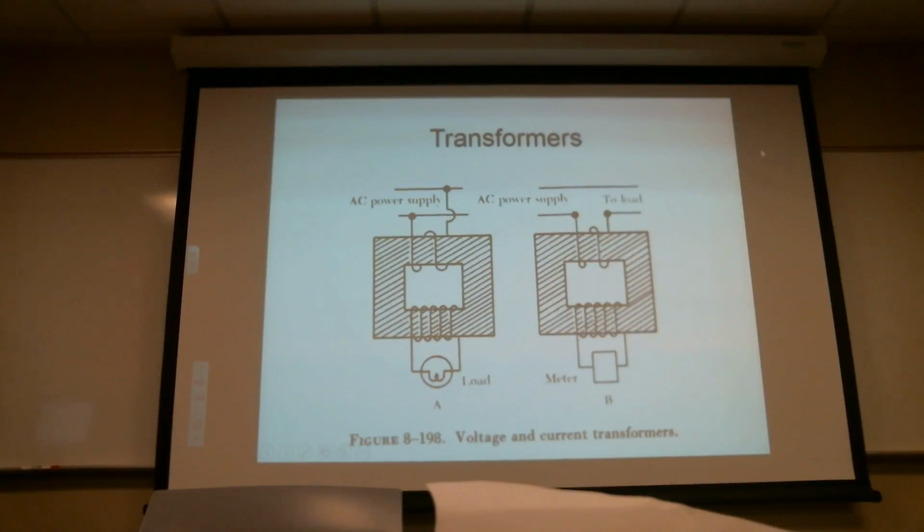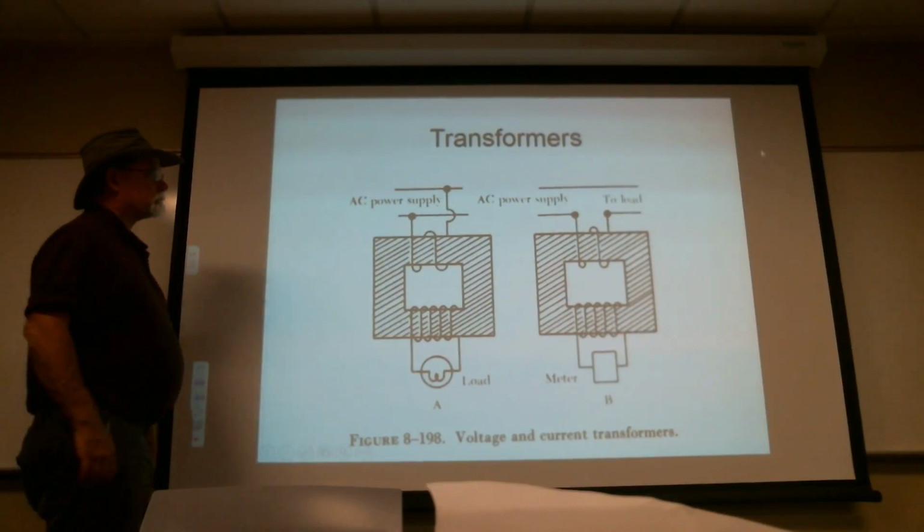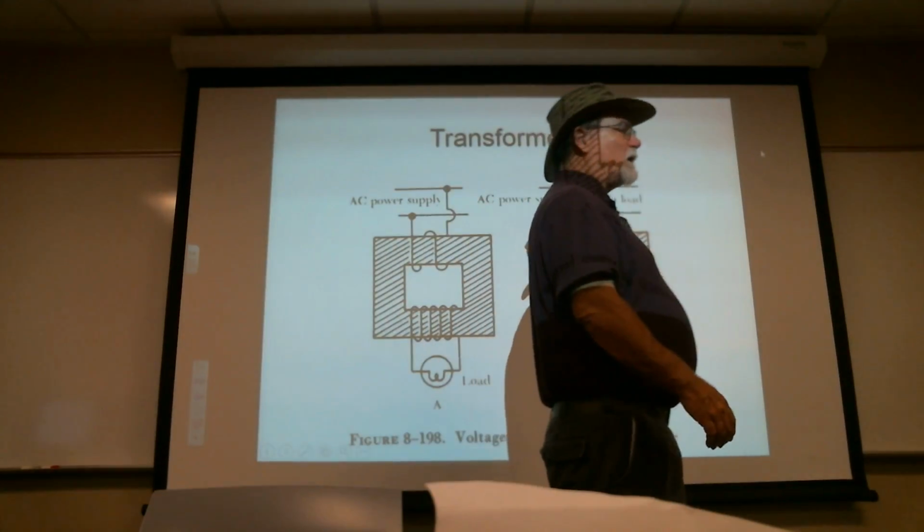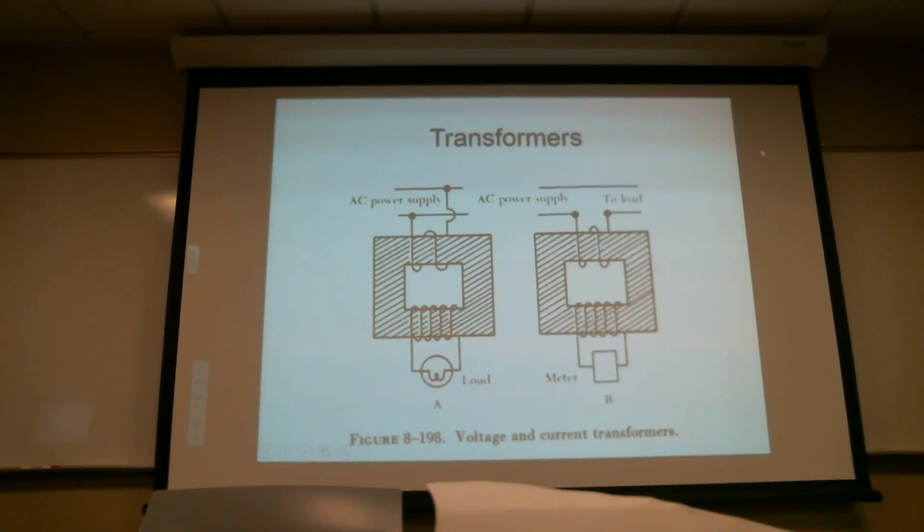The other interesting thing is you could also tap off in a couple of different ways. Given that you've got either a neutral and a hot lead, or two hots if you're in the two sides of the phase, or I can even do it with three phases, I can run a parallel load off of the lines, like on the left, or I can run it in series off of one of the lines.